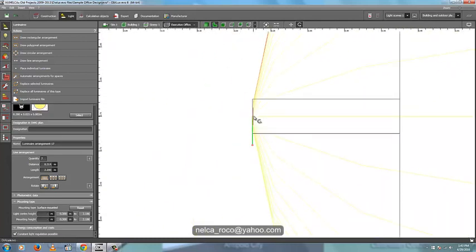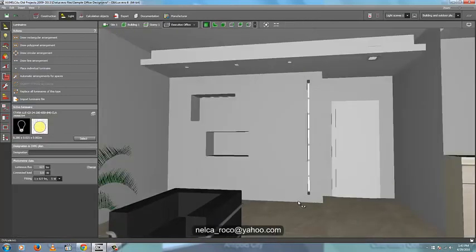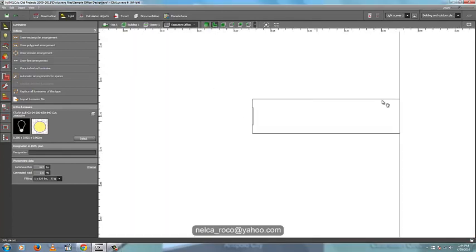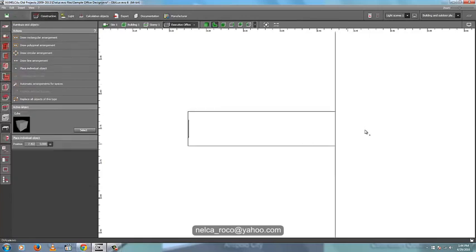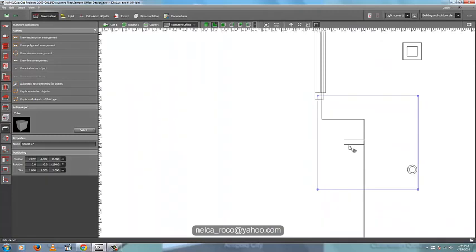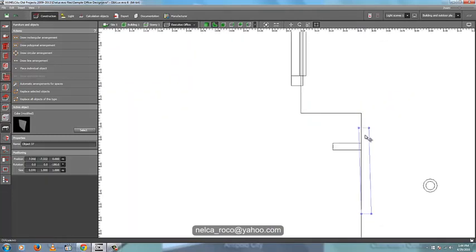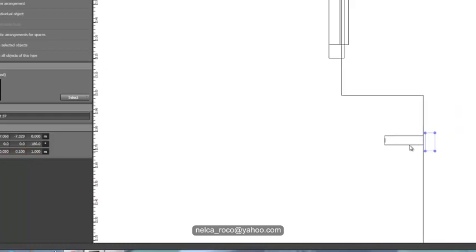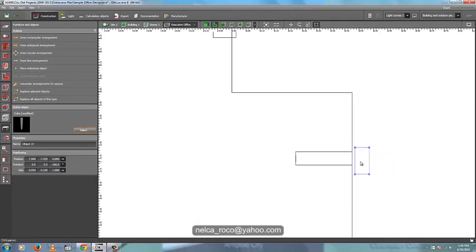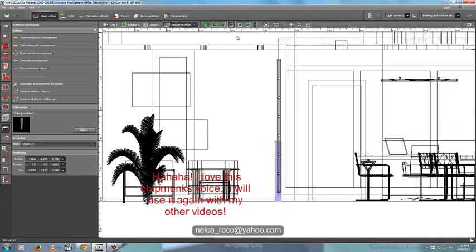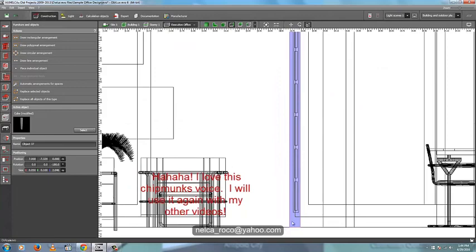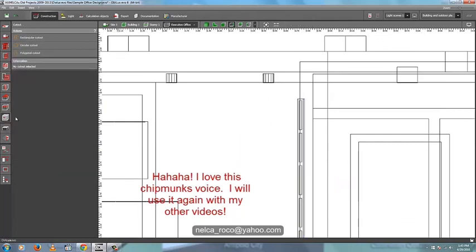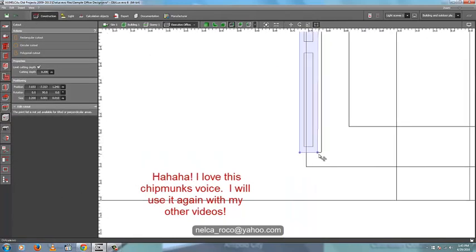And then let's cover this box with maybe a diffuse glass, because it will create glare to the executive officer. So let's go to the object and put box. Let's edit this one. Okay, let's make it 0.05, 0.1, and then let's go to the elevation view to check the height. So let's go and scale. There you go. And this side also, make sure it fits properly on the box. Let's make this hole a little bigger. There you go. Okay, I made the hole a little bigger.